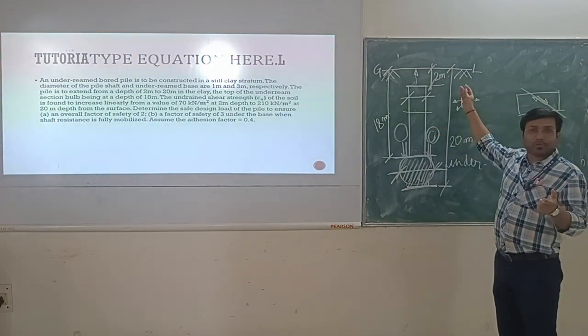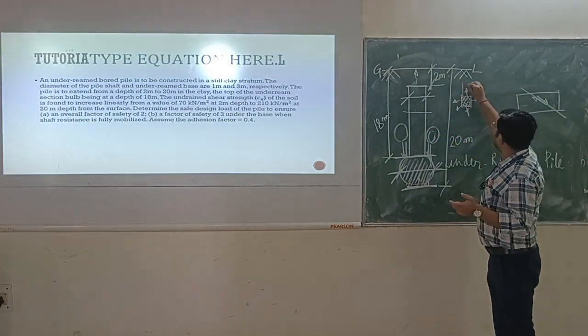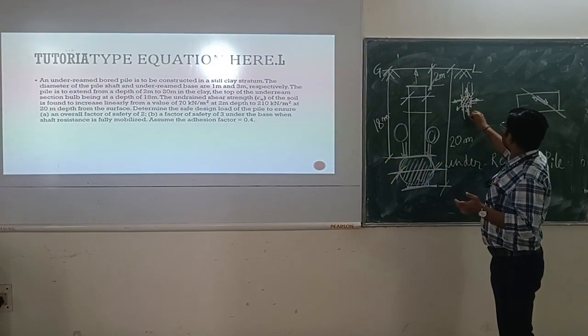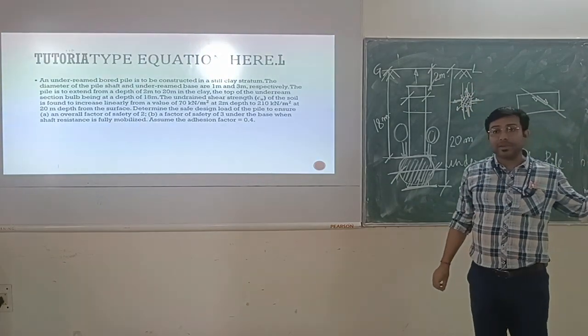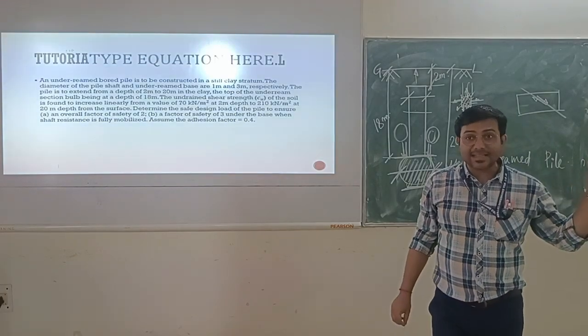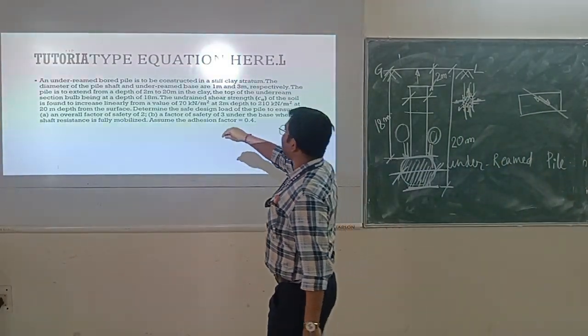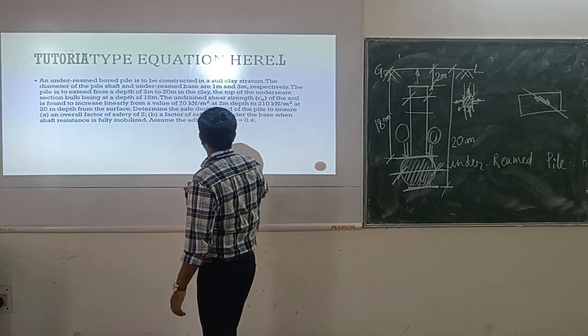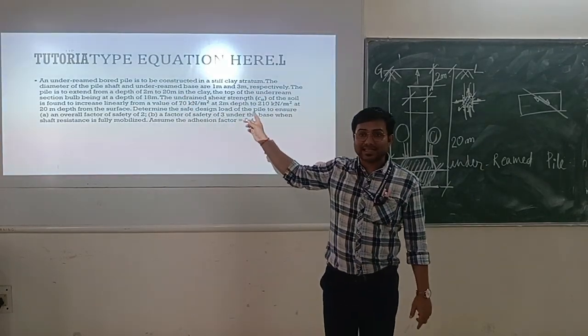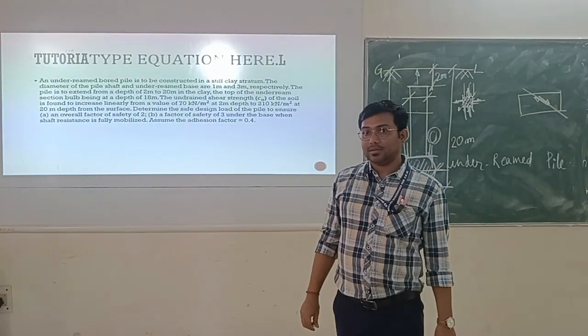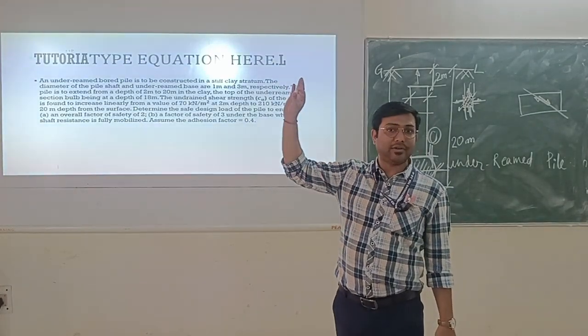How huge an amount of overburden pressure is acting on this. Drainage cannot be possible. That is the undrained condition. And for undrained condition I have given here the undrained shear strength, because we are considering clay soil or cohesive soil. Is that clear to all of you?